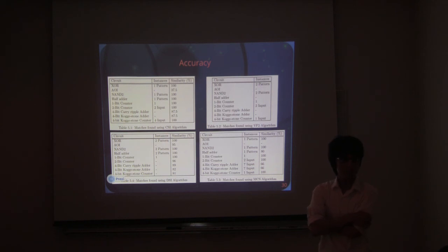Okay. And SAT solvers are very powerful these days. And so I think that is maybe state of the art. You're using more fundamental graph algorithms, right. But you should look at what people are doing with equivalence checkers. Okay. And so that just compares the RTL versus the... Well, there's two versions, right? RTL versus netlist, but also netlist versus netlist. Okay, but it compares to see if two netlists are equivalent. Okay, right.